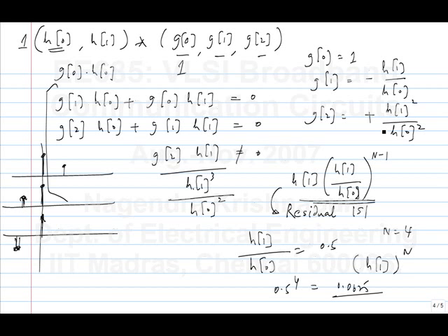Now let's say I give you H. Are there other ways of choosing or is this the best? What was the basis of choosing the taps? I mean, choosing the equalizer taps. I know the channel response, okay? So now I want to design an equalizer for it. I first of all maybe arbitrarily decide the number of taps that I want. Okay, then I go and put those tap values.